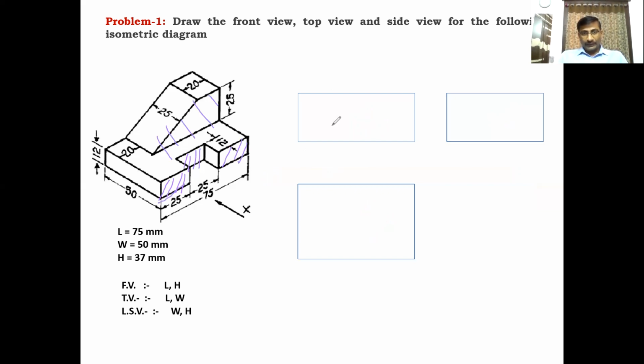Starting from one of the corners, you have to draw a horizontal line. This line is visible from the front side, and this line is visible, a total continuous line like this. This depth line is visible at this place. You have to draw a visible line like this, dot line, and the upper line also appears in this direction. In total, it looks like a rectangular box. Clear? In which these two are vertical edges in that view. Also this surface is a visible surface. You have to draw these surfaces in the front view box. Clear? So start the diagram.